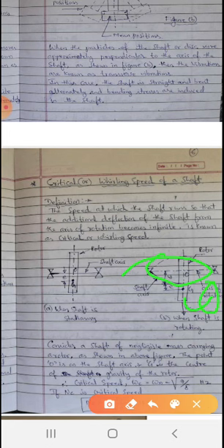Due to this, the shaft is subjected to centrifugal force when the shaft rotates. This centrifugal force bends the shaft, which further increases the distance of the center of gravity of the gear or pulley from the axis of rotation of the shaft, and in turn further increases the value of centrifugal force, and thereby once again increases the distance of the center of gravity from the axis of rotation.